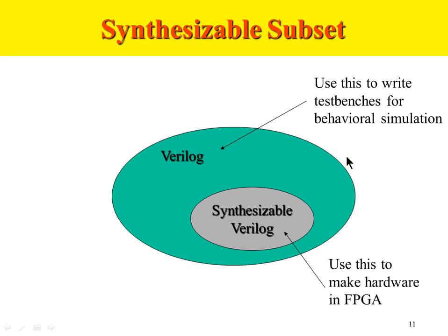A test bench is a testing environment. I will never implement a testing environment on the chip. I just use it to test my design at a simulation level. Then the design itself will go on the chip. The test bench, which is for testing purposes, will remain at the software or simulation level. So for writing test benches, I can use the entire Verilog, but for synthesis and implementation on hardware, I can use only the synthesizable subset of Verilog.